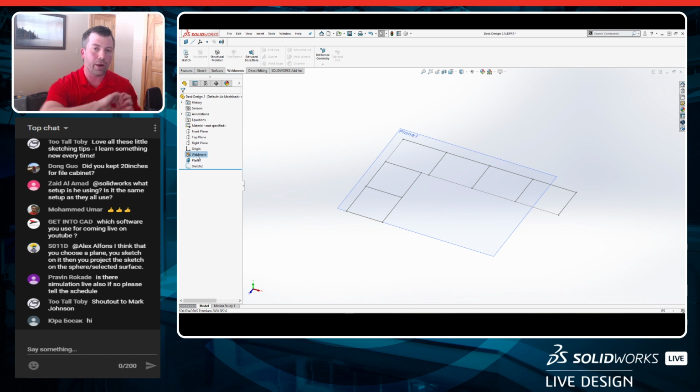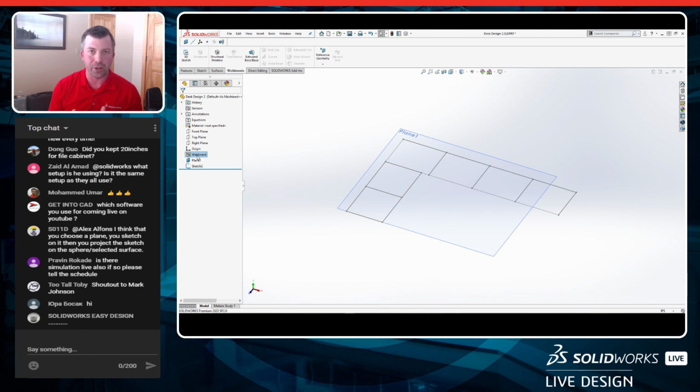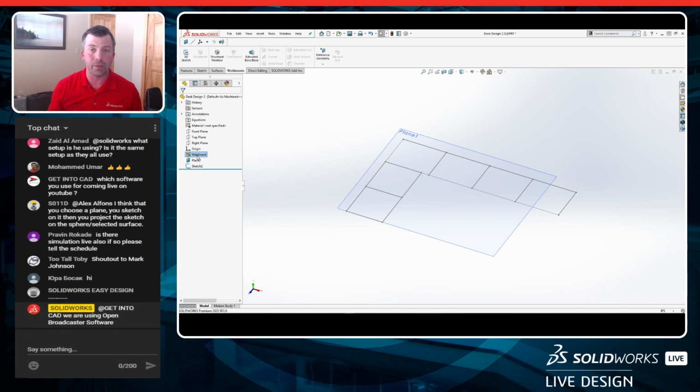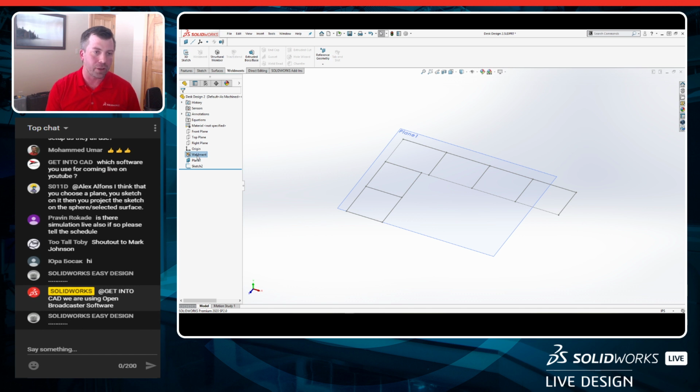Now, this is going to tell every downstream feature to not do that merge, right? We want to create a multi-body design for this whole thing, so no parts are ever merged together. Keep that in mind because you can use that functionality if you're using a master model multi-body approach. Maybe 3 cylinders and you always want those to be not merged. Just enable Weldments, turn it on, and it just by default takes away that merge result when you're creating an extrude. Super cool little pro tip. Really awesome for that master modeling, single part, multi-body design technique.